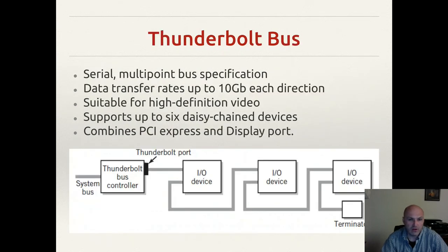Another bus I want to talk about that's been around for a long time, but not quite as popular as USB, is Thunderbolt. And Thunderbolt is important for a single reason that I really want to talk about that most people don't realize that it even has. This is another serial bus, just like USB and PCI Express. In fact, it is very much like PCI Express because it is in fact an extension of the same bus.